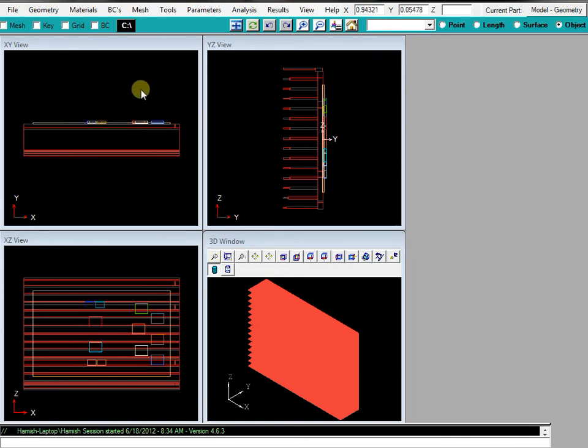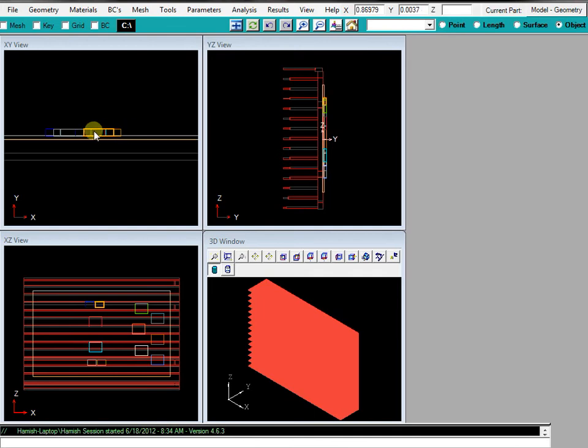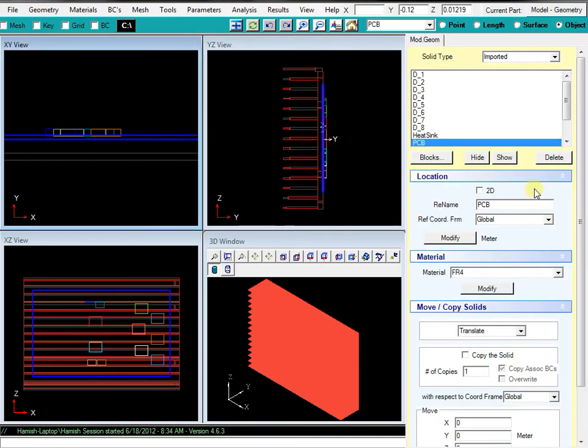For this, we're not even going to worry about the traces on top of it because we don't know what they're going to be. So instead, we'll just model the components going directly into the dielectric layer. We'll skip over that with no resistance between the component and the dielectric layer. So to start with, we don't want the PCB to be FR4, so we'll change the entire PCB and make it copper. I'm not exactly sure what copper it'll be, but we'll just use pure copper for now until we know what that is.